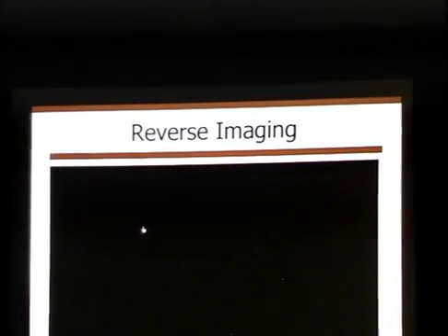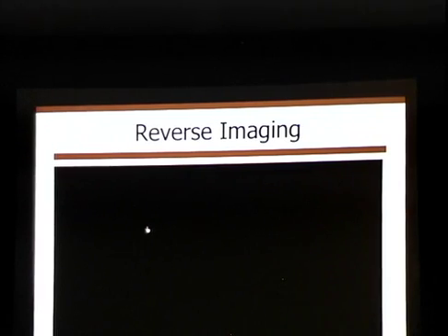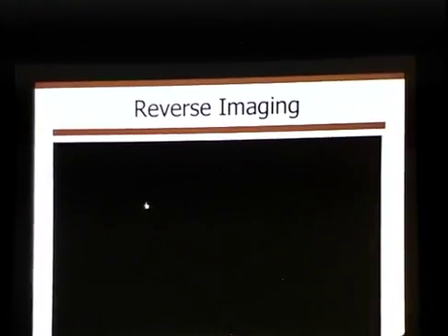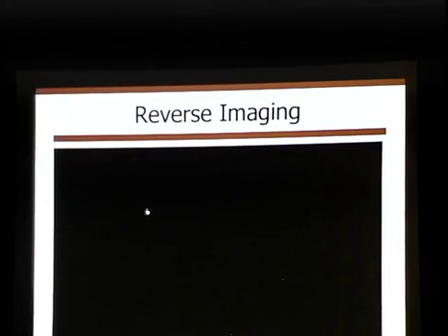And so this is a piece of hardware that's kind of like BitTorrent. It doesn't care where the sectors come from, it doesn't care what order they're in, but it'll go forward and try to read the sectors that are good as fast as it can, and then in reverse, it will try to read the ones that were bad that it couldn't read the first time around, filling in those holes as it goes.